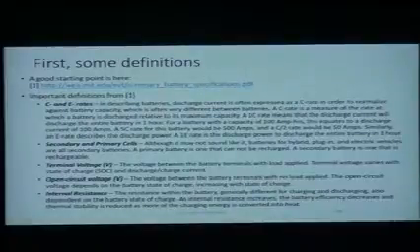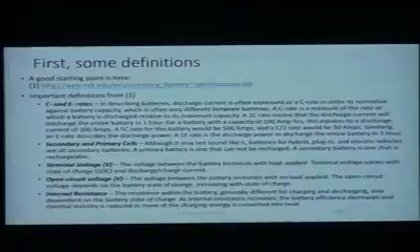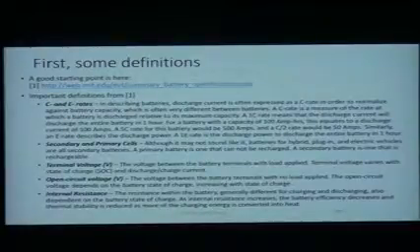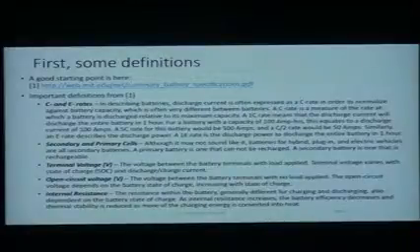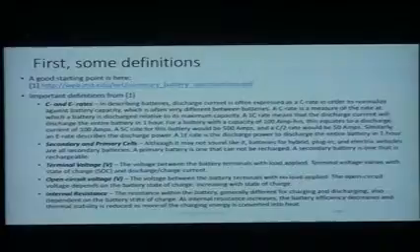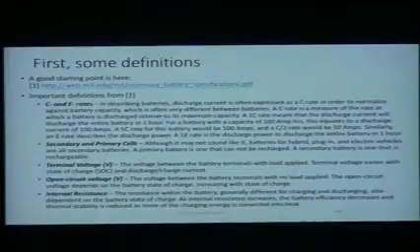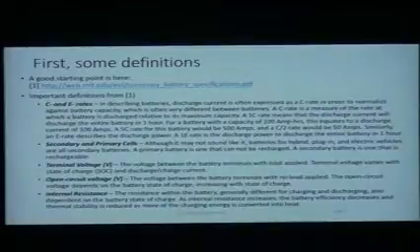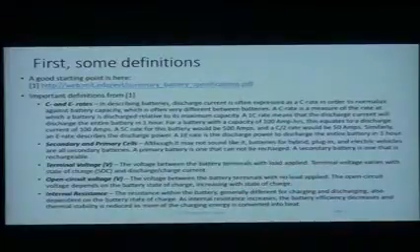So the first thing is, when I test a battery or supercapacitor, at what rate should I be testing it? It seems like a really simple question, like you could just pick something and go. But it's really not fair to compare performance of a big battery to a small battery unless you are somehow normalizing for their size. And so the C rate is something that you'll see used often. The C rate is the rate of current draw that you're taking out of a device in order to discharge it fully in exactly 1 hour. That way I can take a device that's really big and heavy, a large battery, and compare it to a small battery in a fair way. So that's what C rate essentially means.